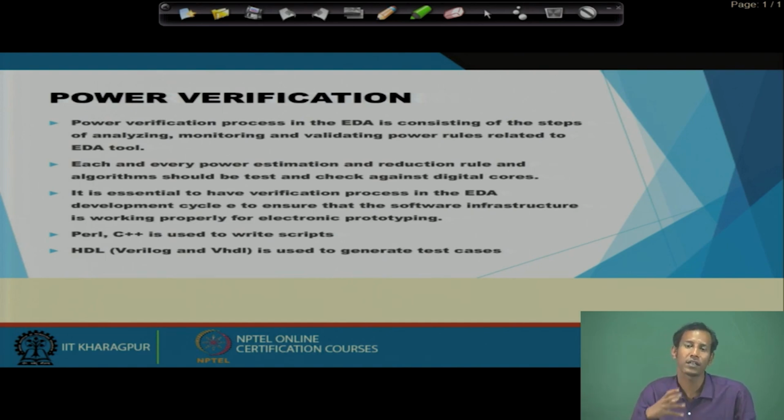So, at that time I will try to consider how I can apply different techniques to reduce the power consumption on that particular block. Why? Because in today's complex system design there will be so many sub blocks. If I use IP-based design, so many IPs are connected. Among them, which IP contributes how much power in the overall power budget of my system? I have to know and identify that, and then according to that I can take the necessary steps to reduce the power consumption of that particular block.